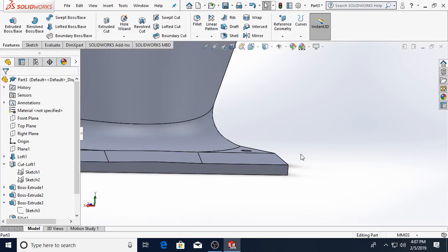If you were actually designing parts, something that you bear in mind when you're creating intersections of parts is something called stress concentration. And chamfer or chamfer is a common way to try to minimize stress concentration. If you chamfer your corners, then you give it more area to disperse that stress, and it doesn't concentrate in one place, which is likely to fail. Questions on fillets and or chamfers?